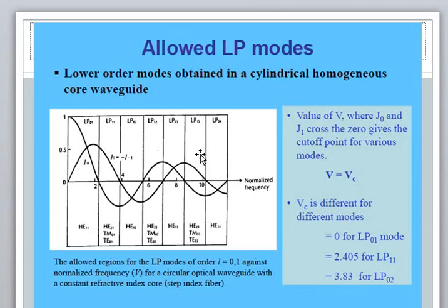There are the hybrid modes. For a dielectric fiber waveguide, all modes are hybrid modes except v equal to 0. Here v is the order, and that order may vary: if there are 3 orders, the v value may be 0, 1, 2. Then m is the mode number, the first mode or second mode.